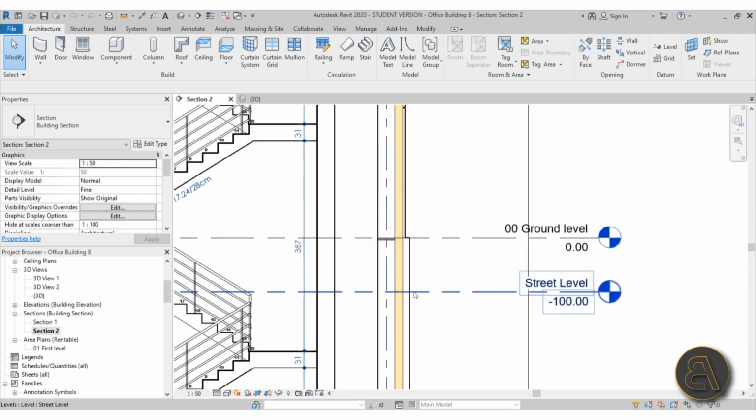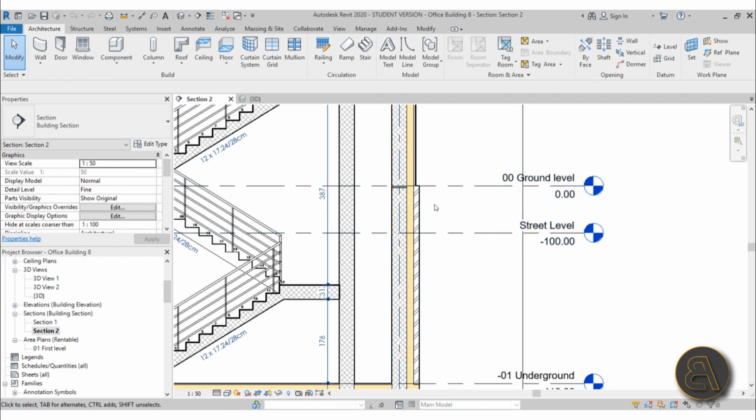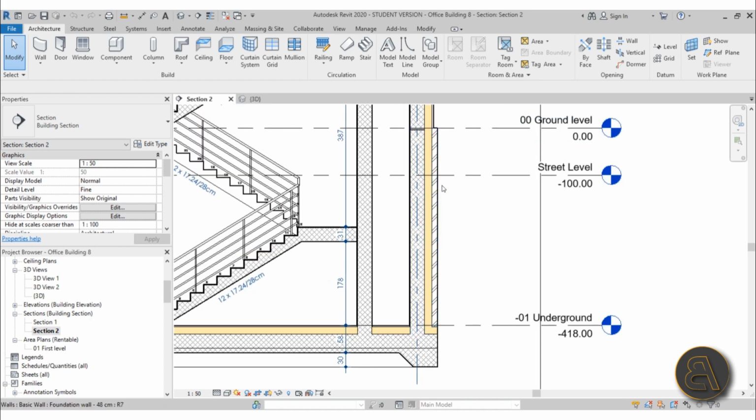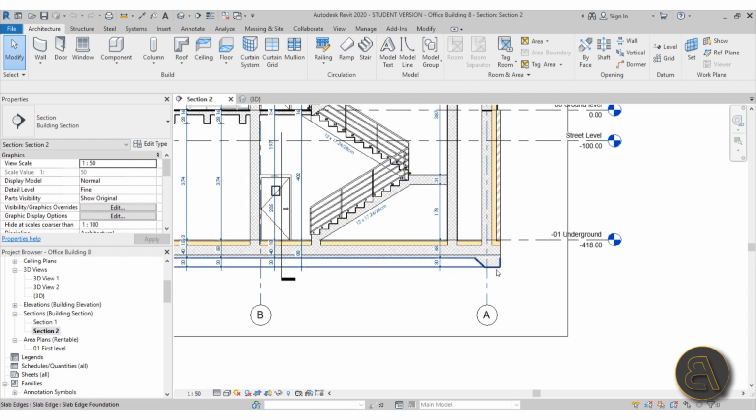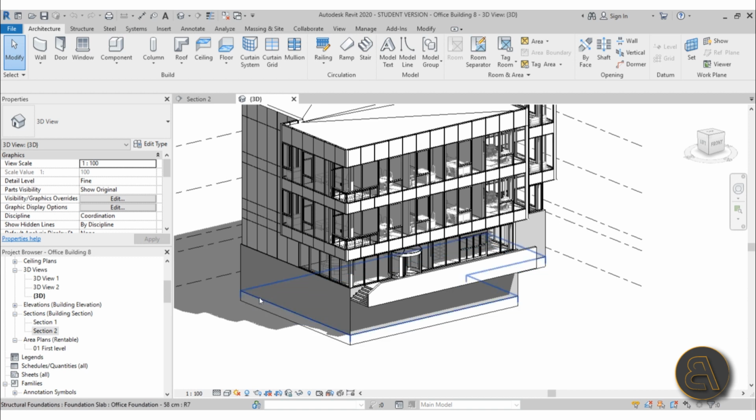The problem with that is water comes running down this wall from rain and all of that. And when the rain is collecting here, it might go underneath your foundation, and then it might start eroding the ground underneath your foundation. And if the ground gets unequally eroded in different places of your building, you might get cracks in the foundation. Now, to mitigate that, you add a little bit of a skirt, so to say, around your building, and you do that just as a small piece of sidewalk.